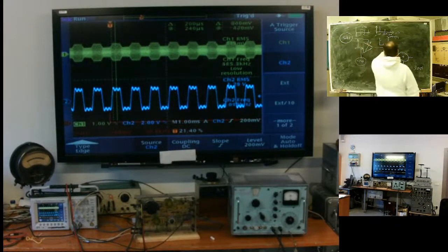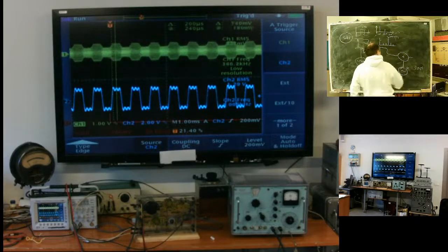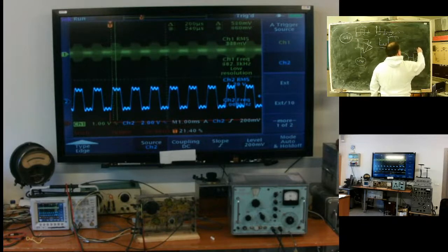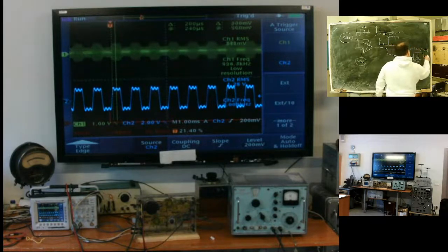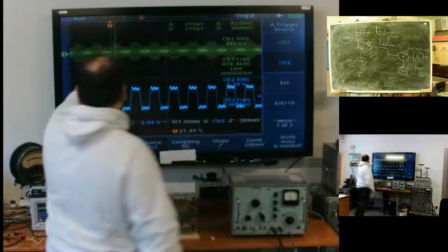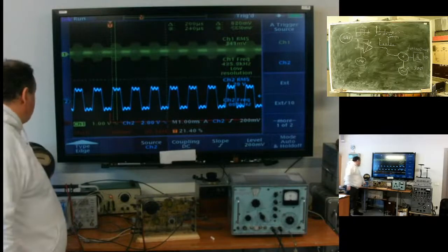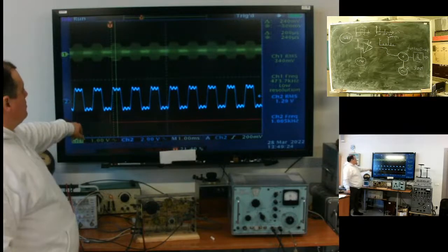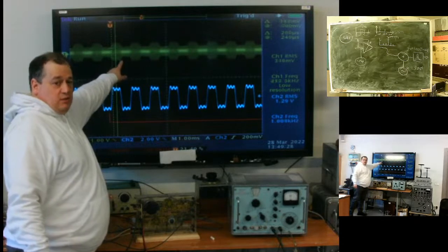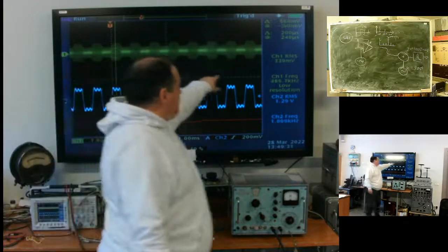my signal with a spectrum around 300 and put through the filter with the frequency around 460 kilohertz, central frequency. And what do we see? Looks like it's an amplitude modulated signal, yes? But at a different frequency.